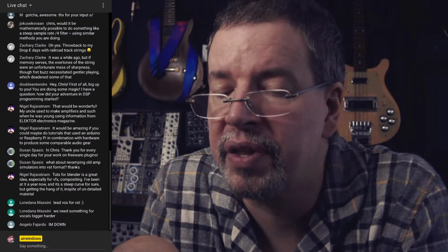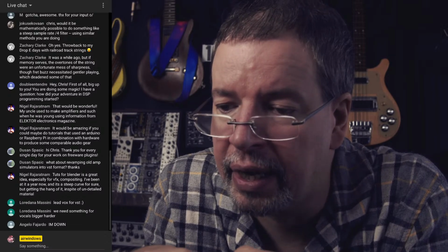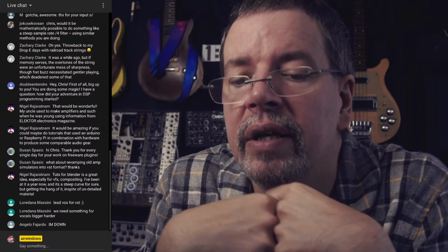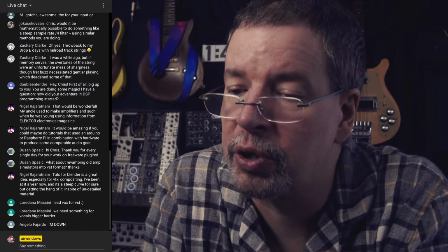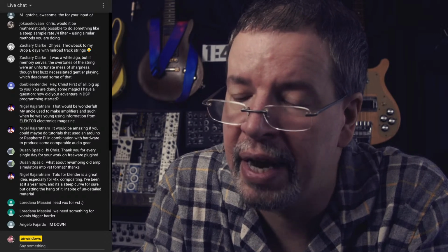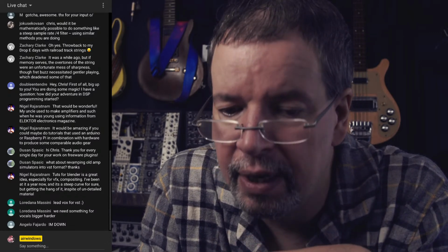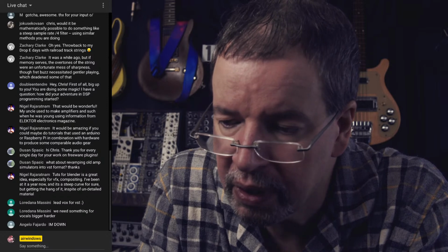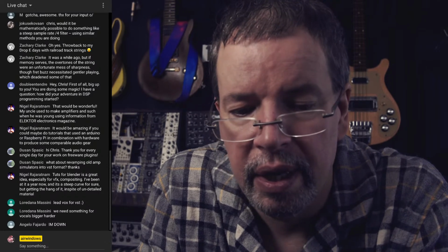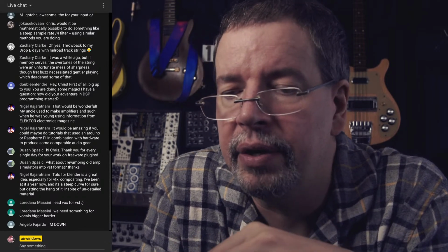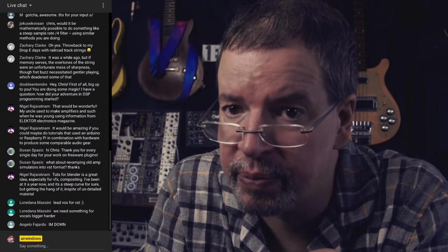It's wired up so that it uses a XOR logic gate, and I have those too, to generate a long series of random delays between on and off. It has to start up with at least one positive voltage in the shift register. But then once it does that, it just runs at a really high frequency, like 300 kilohertz, and it just goes. And what you get out of it is white noise. It's 1-bit white noise that is a fairly good approximation of white noise.